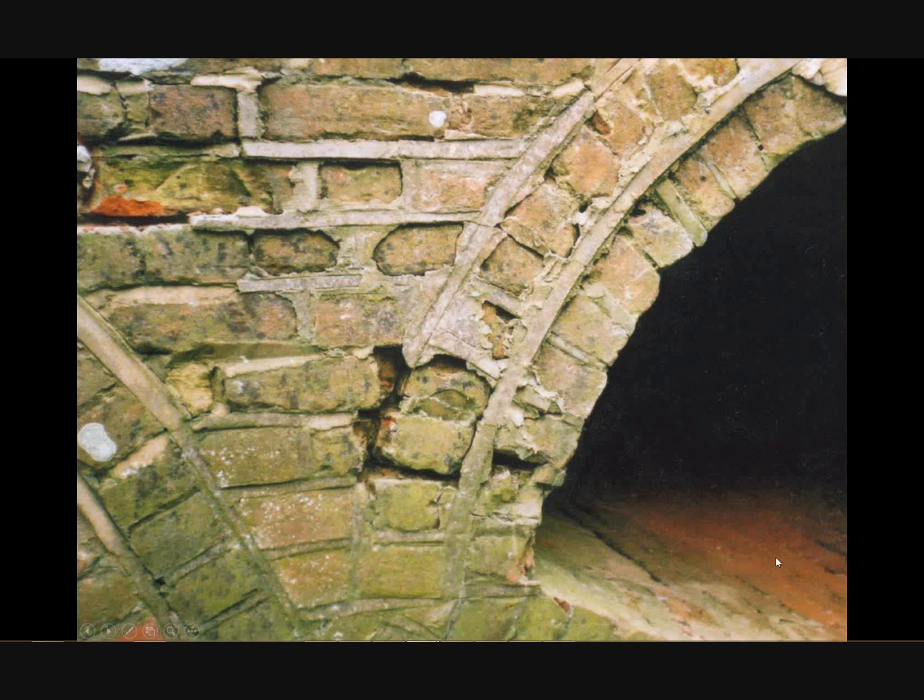So if we actually look at the bridge itself, it's in pretty poor condition. You can also see it's multi-ring brickwork. But if you look in the region around the bottom right, you can see that the outer span has got a masonry invert. So what it means is that the base of the central piers are going to be prevented from moving.